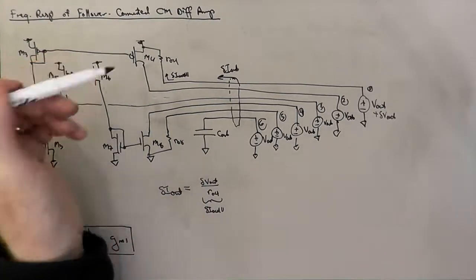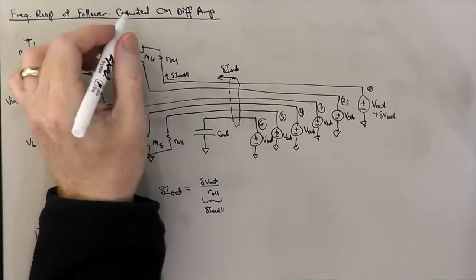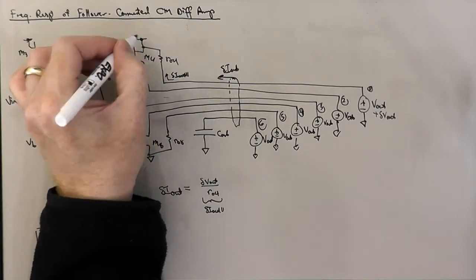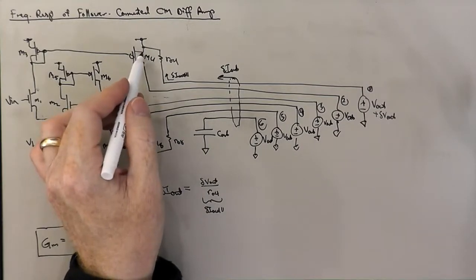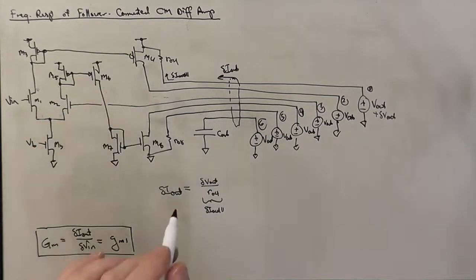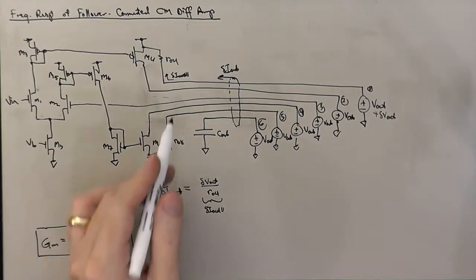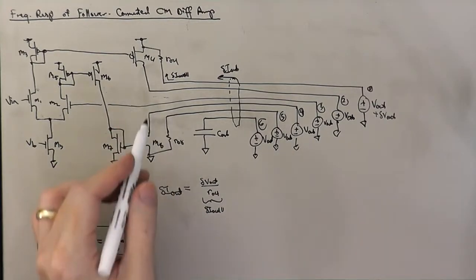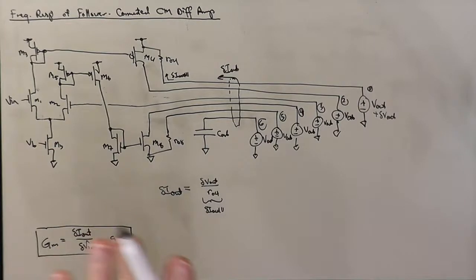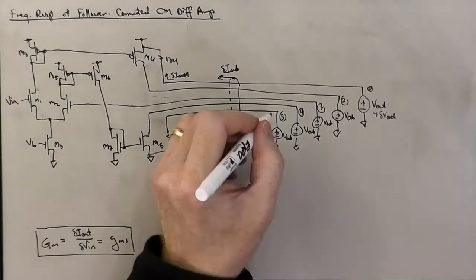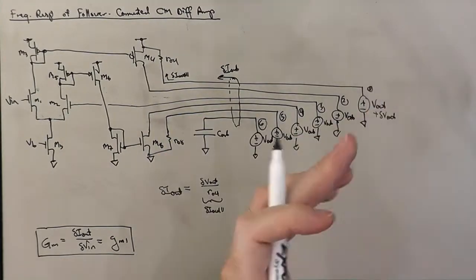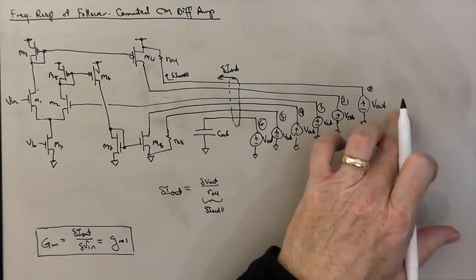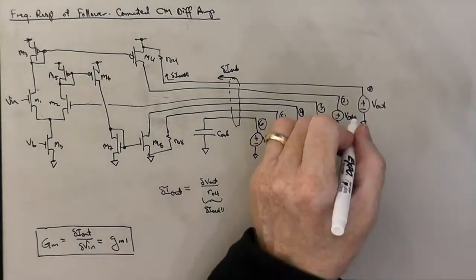And notice that that flows directly back to the power supply. It doesn't affect the voltage on the power supply at all to absorb that little bit of change in current, and so it has no other effect anywhere in the circuit. It doesn't flow back to the source of M4, it just flows back to the power supply, and that's all it does. So of the 6 possible components due to delta V out on branch 1, we get just one non-zero component. So move on to number 2.